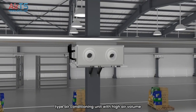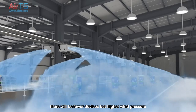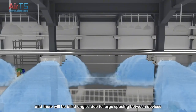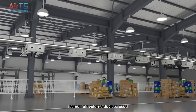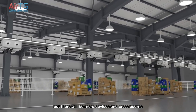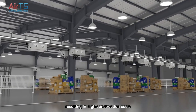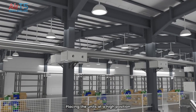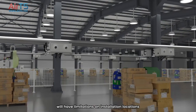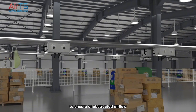If a jet flow type air conditioning unit with high air volume is adopted, there will be fewer devices but higher wind pressure. People close to the devices may feel uncomfortable, and there will be blind angles due to large spacing between devices. If a small air volume device is used, the overall temperature field balance can be improved, but there will be more devices and crossbeams need to be installed between adjacent columns, resulting in high construction costs. Placing the units at a high position will result in larger blind angles below, while placing them at a low position will have limitations on installation locations and require avoiding obstruction from production devices to ensure unobstructed airflow.